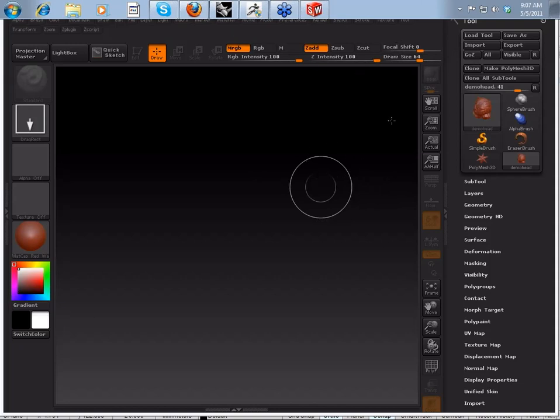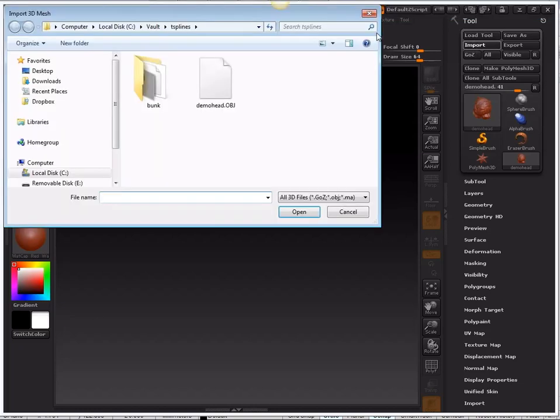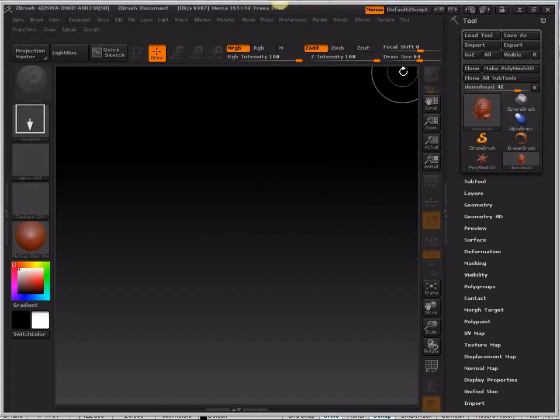Okay, so I'm going to show a really powerful workflow that allows you to bring the scan data at whatever level that scan comes in at and be able to retopologize it in ZBrush. And a side benefit to this retopology tool inside of ZBrush is it converts any scan that comes in as triangles into quads, and T-Splines loves quads.